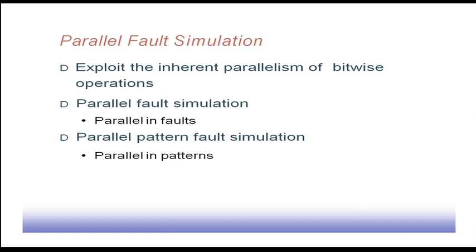So people have started looking for a faster version of this fault simulation process, and accordingly many other simulators have come up. One of them is known as parallel fault simulation. Again, the same thing as we were talking about in logic simulation: we have these word sizes of the processor or the computer on which you are running the fault simulator.